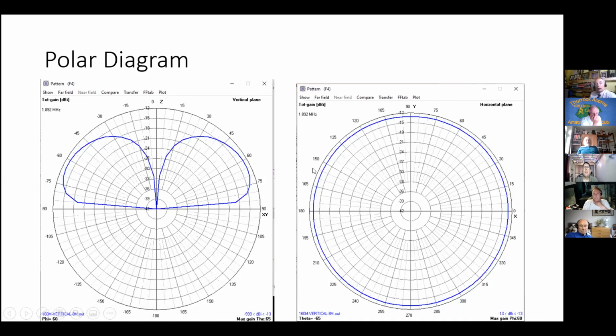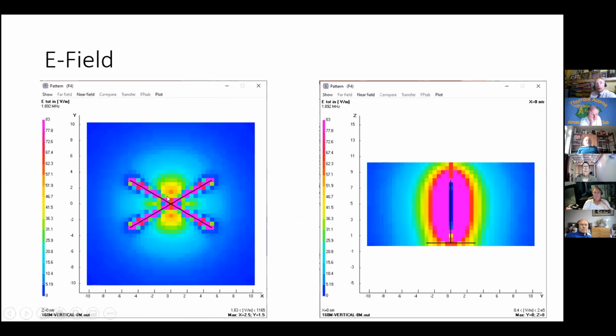Omnidirectional, as we'd expect. If we actually look at the near field, the slight asymmetry, just moving those ends closer together, results in a distinctly lobed radiation pattern above ground. The radials are hot for about 1 meter around. I think from memory I did that with half-meter squares.